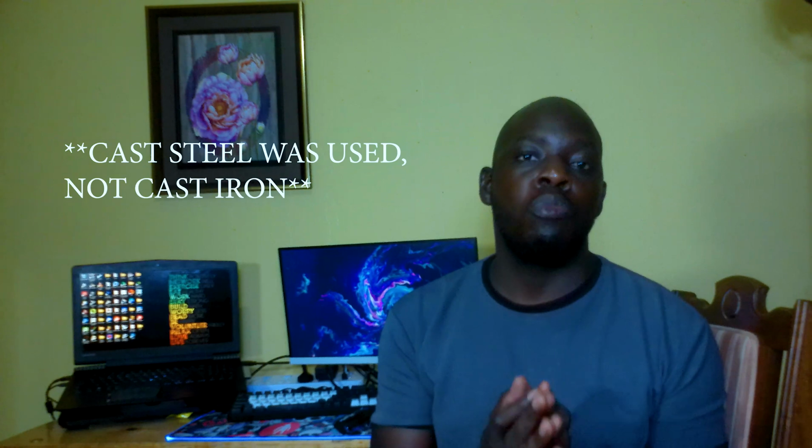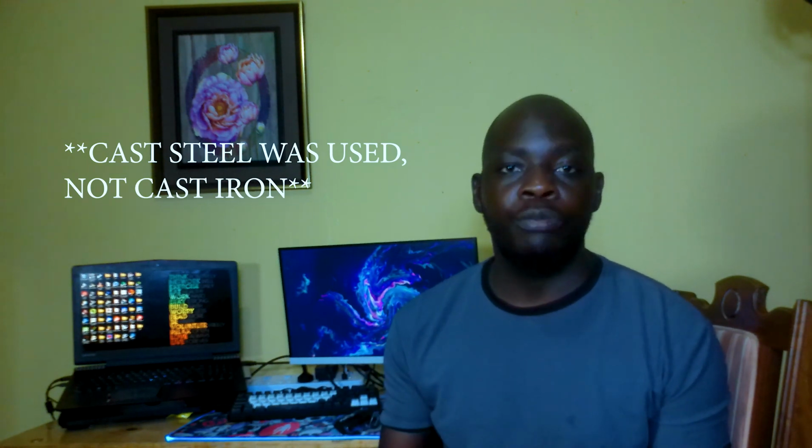So ideally, cast iron and cast steel are mostly used in modern day exhaust manifolds in your cars. But what if the company we're working for, ideally, in our imagination, wants to use a different material? So what we'll do is compare the material that we want to produce our exhaust manifold with cast steel. And in CFD, we'll have two materials: cast iron, which is used in modern day production of exhaust manifolds, and our material B.